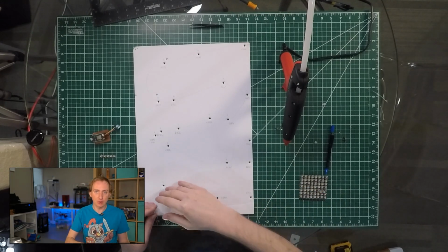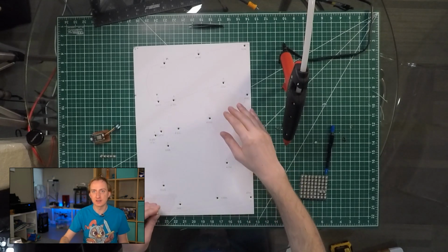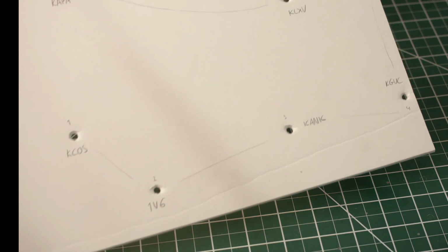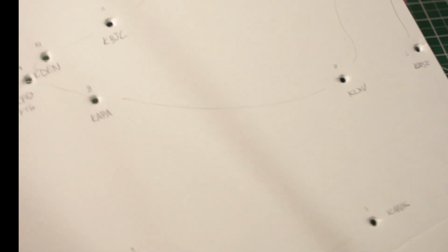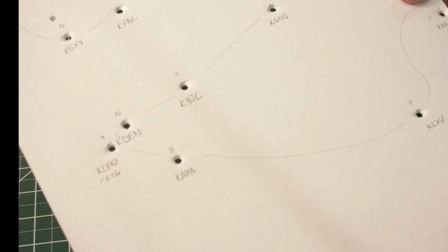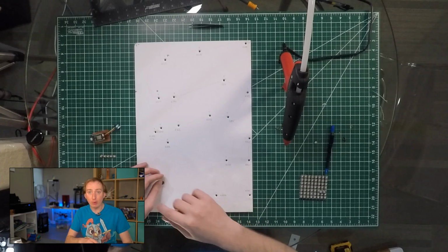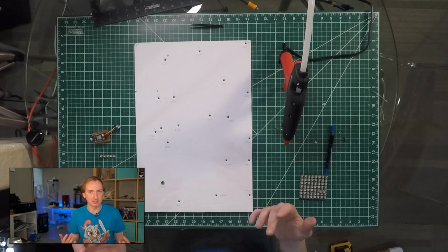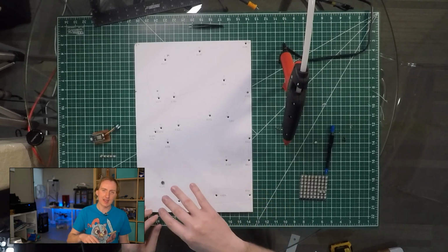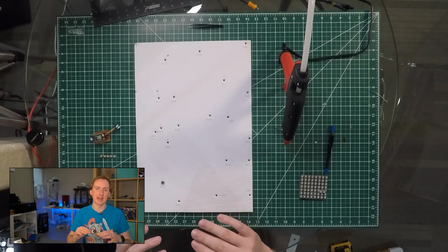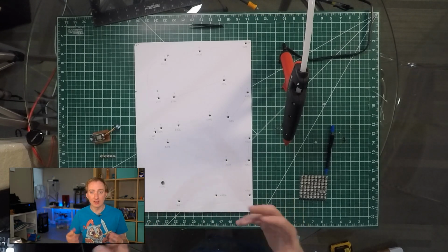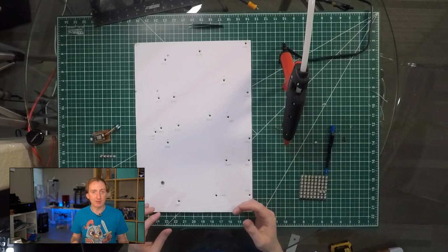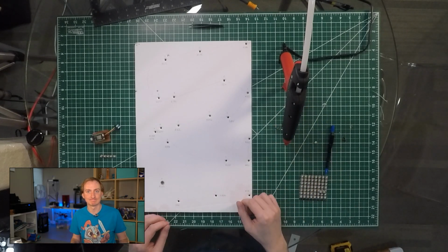That means working out what the path of my wires will be, which you can see here. I've traced out a rough outline on the back. When I glue the LEDs, I'll lay them down so the arrows point down the path. That means later when I come to solder them, which is the most time-consuming and laborious part of this process, I have a decent chance of all the wires lining up and not getting too much wire strain. So that's just a quick note. Now the hot glue gun is almost there, so we'll cut to a time lapse and I will start gluing these in.